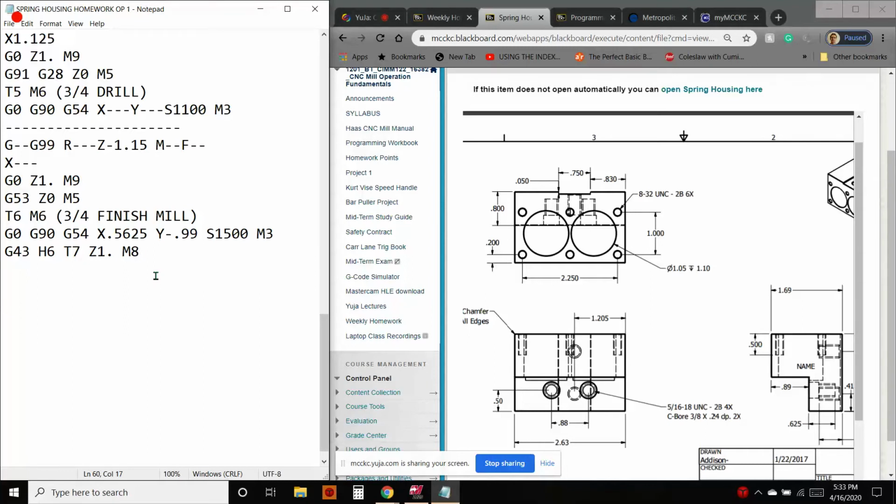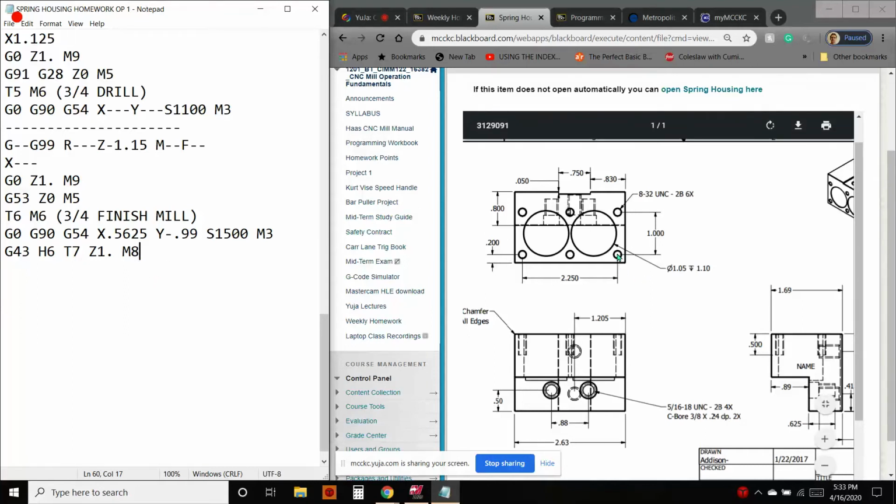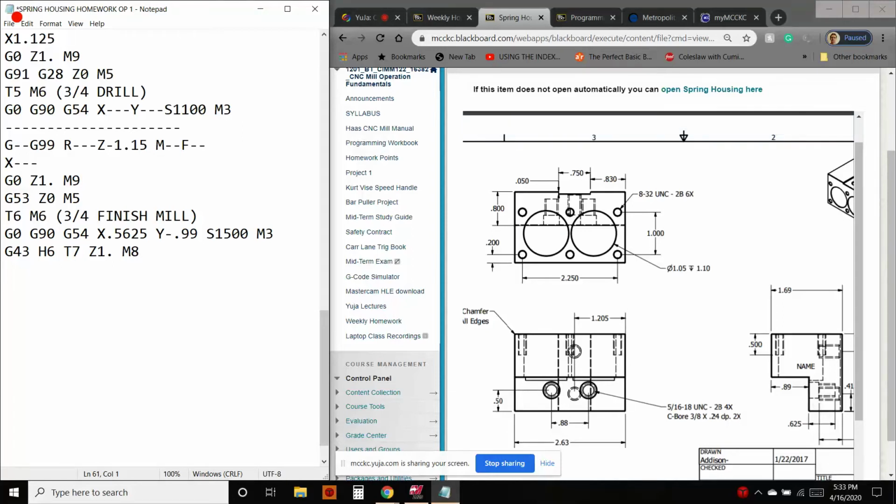We're on the right side bore, and we're right centered on the right side bore. The smart thing to do here is feed down at a higher feed rate so that you don't have a production delay, but if you happen to change the tool and got your tool length offset wrong and walked away, it wouldn't crash into it so hard. So we'll say G1 Z0.1 F50 inches a minute. All right.